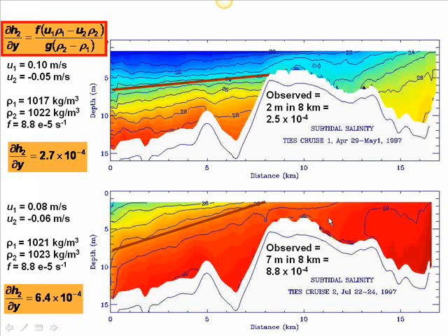Because it's shallower. The bottom effects affect a greater portion of the water column here than here. So the greatest slope means that there's more mixing. So we have a departure from geostrophy. Geostrophy doesn't apply over this entire section. It's almost as if we had two different estuaries right there at the entrance: one that's in geostrophic balance in the channel, and one that is strongly frictional over the shallow area. So this is something to consider. It's quite interesting.